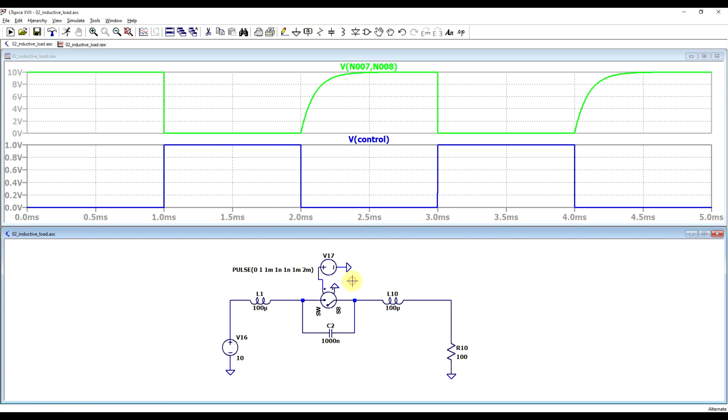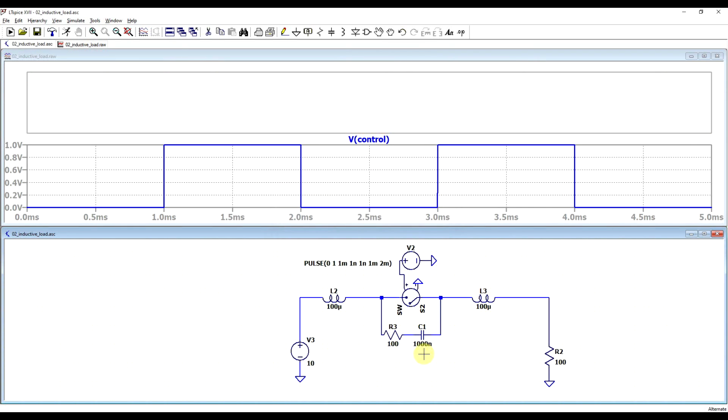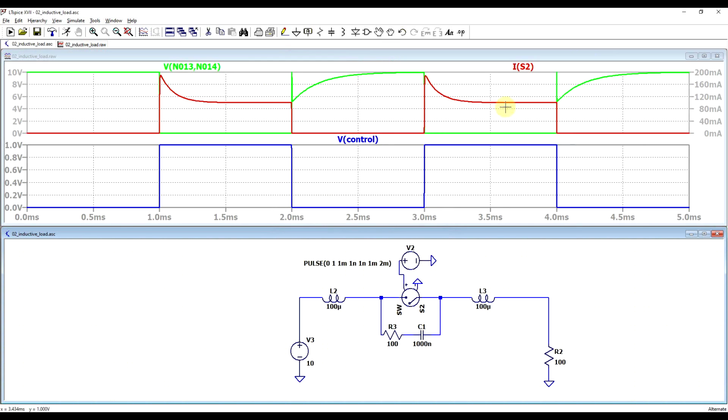The only downside, of course, is that when the switch is closing, it will be exposed to very high currents, since it's basically short-circuiting the capacitor. So the obvious way to counteract this is to add in a series resistor. By doing this, the switch will get exposed to some small voltage spikes, but at least you will no longer have overcurrent problems. The exact value of the voltage spike and the current running through the switch will be determined by the two component values.